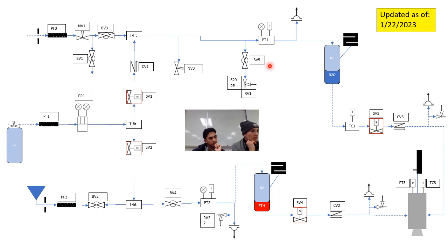So at this point, we've closed everything except for SV1 and SV2, and we can close those. Somewhere around there, we want to check for nominal pressure and temperature values. We'd like to see the increase in pressure and see that there's not an obvious leak at 15 psi, because if we're leaking at 15 psi, it's not a good sign for our much higher pressures. It's one of many times we'll be checking whether our instruments work properly as we add gas at increasing pressure.